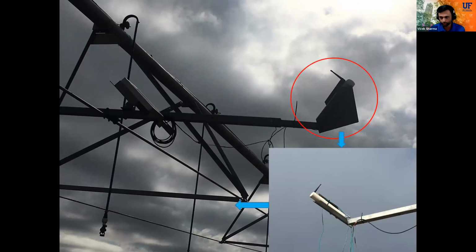For example, this is showing you, sorry for the dark image, the canopy temperature sensor installed on the pivot so that it can sense the canopy temperature when the pivot is moving itself. Over the last decade, a lot of research happened on that, and generally those instrumentations are used to collect the canopy temperature data at one particular point, again on a rotating event. So there is an average area, and you will get an approximately average value of canopy temperature from that area.